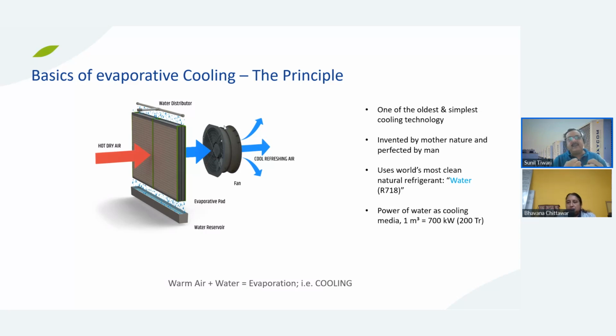Means actually, as much as the temperature is dropping, the sensible heat of air that you are removing, you are adding it back into the air in the form of vapor, which is nothing but the latent heat. So the total heat, the enthalpy, remains constant, it doesn't change. But what happens? The temperature is lowered, and that gives you the feeling of comfort, and that meets many of our needs where we don't have to resort to more energy guzzler air conditioning solutions.